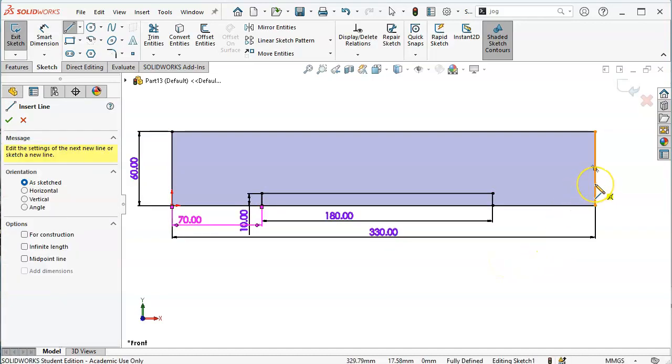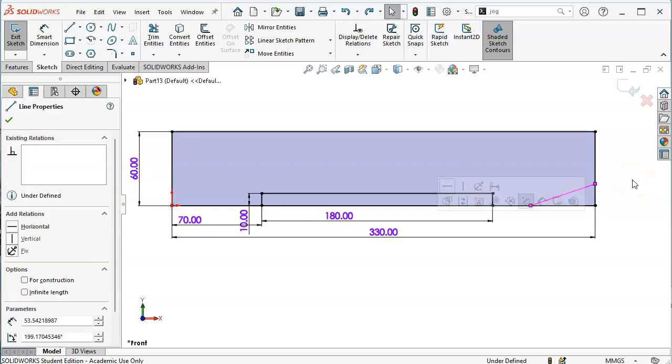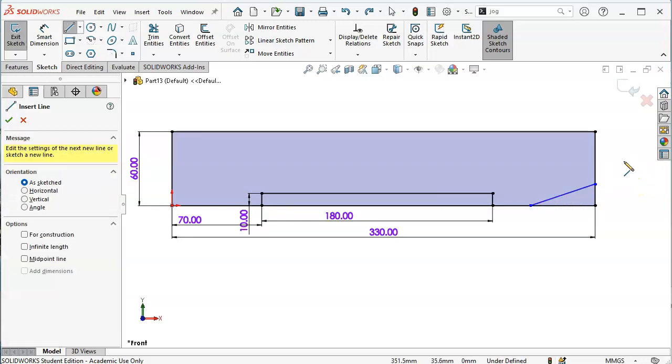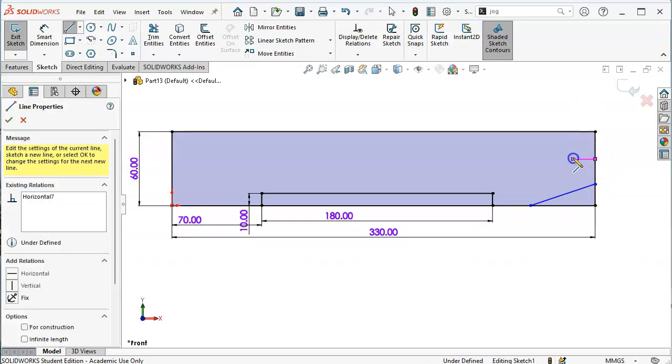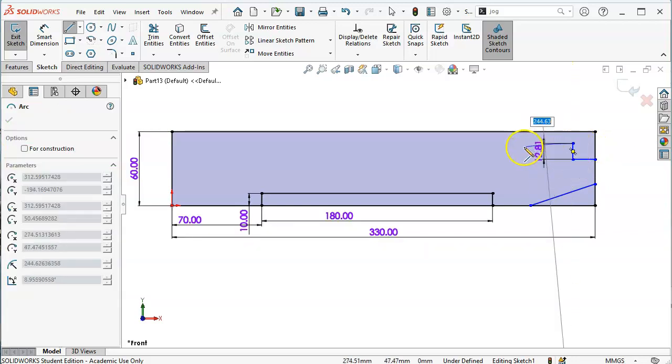And then we're going to go back into the line. We'll pull that back. And watch out for that midpoint. Nothing I can really do with that except complete it and then undo it. But watch out with the undo even, because there are times where it's going to undo more than you would really like. So this one is giving me the chain dimensions where I can do the 12.81. I just can't move the mouse while I'm putting that value in there. All right, and that kind of shifted me into arc mode.